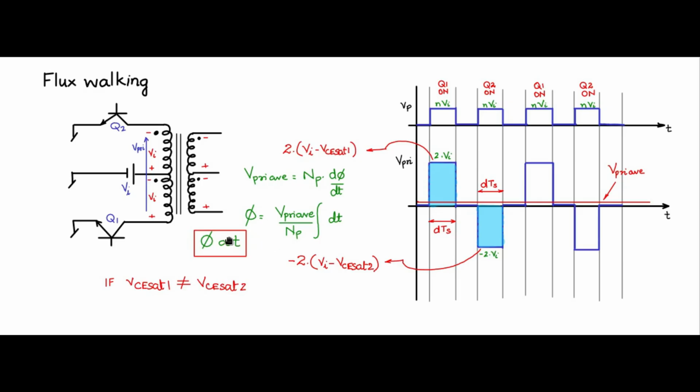But still, you will have a problem: initially the circuit will be working, and after a few months, once the flux saturates, you will see misbehavior. It may be catastrophically damaged by blowing up some of the components. The operating point keeps drifting depending upon whether V primary average is positive or negative.